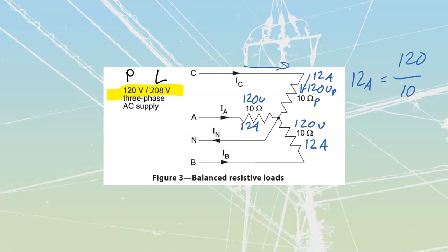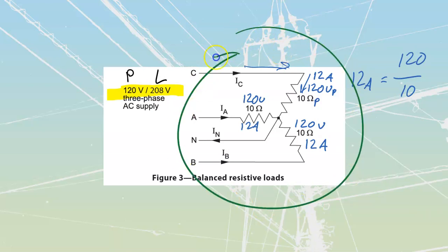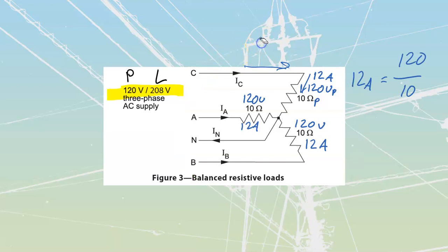Well, the first thing that we're going to do is recognize the fact that these are constantly rotating. Remember, we talked about phasors, vectors, and scalars. They're phasor values, which means that they're constantly rotating around, but we're going to freeze them in time. We're going to pick one of them as being our reference. We're actually going to pick the A line as being our reference, just because I prefer that one. And so if I would freeze time, I would take this whole circle, or this whole delta that's constantly rotating, and freeze it so that my A is at 0 degrees.